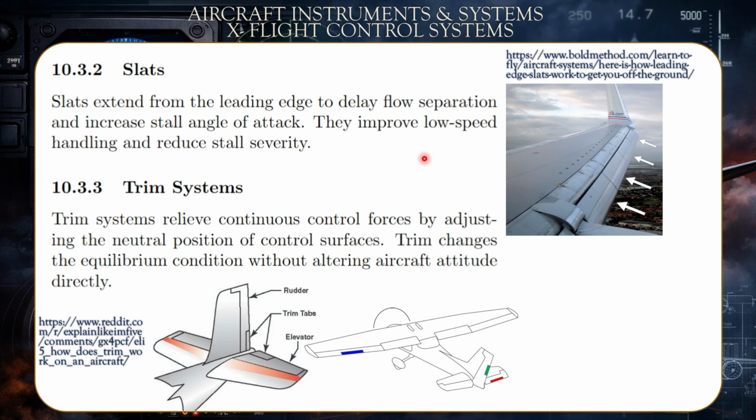So two objectives are accomplished: slowing down the aircraft, reducing the airspeed by increasing drag, while at the same time reducing the descent rate, or the VSI, so as to enable the aircraft to touch down at a lower descent rate and lower velocities.